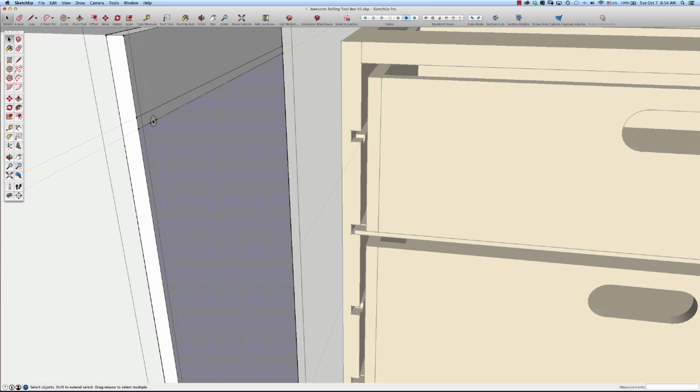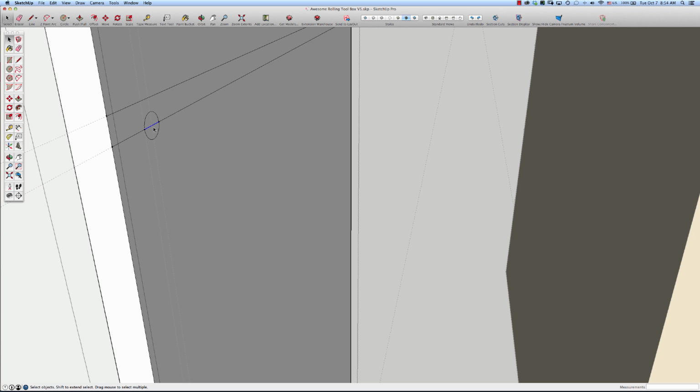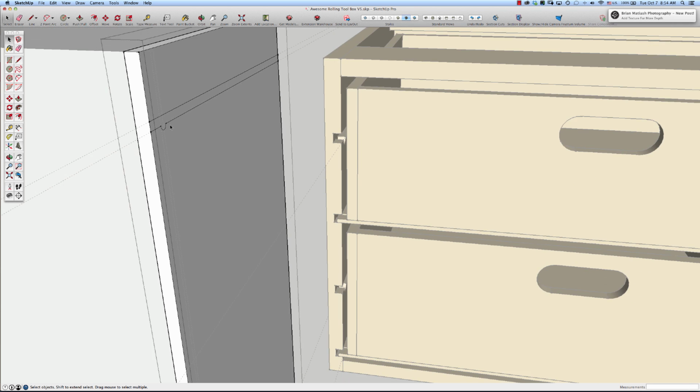All right, so now I've got the lines breaking the surfaces, but I don't need part of the circle. This will be all one cutout, and I'll make a template to do this with a router. So I will remove the top section of the hole and the line. And now I have the layout for the cut.